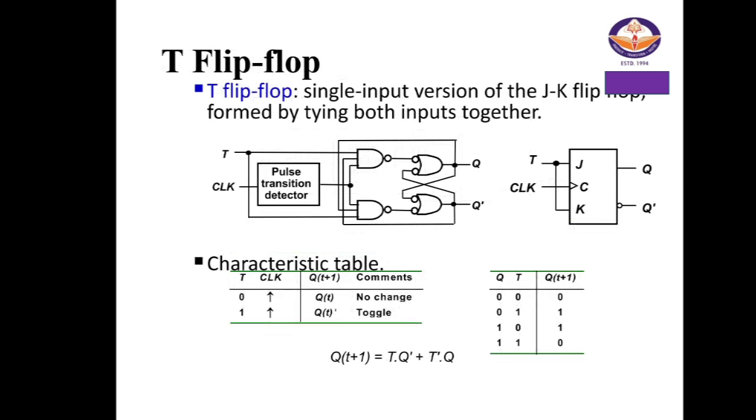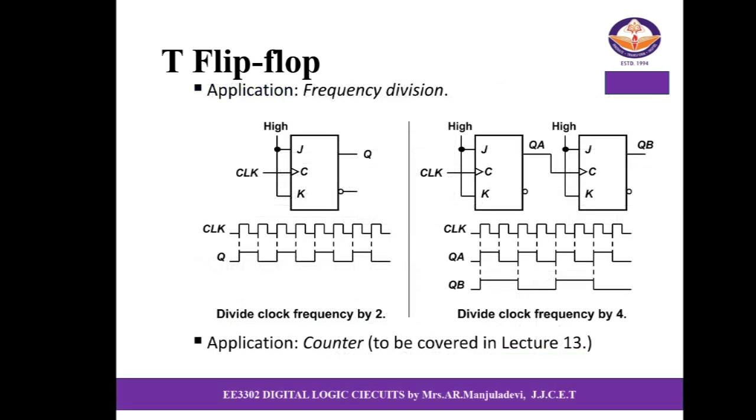Next, T flip-flops. It is a single input version of the JK flip-flop formed by tying both inputs together. This is the logic diagram and characteristic table of T flip-flops. Applications of the T flip-flop are frequency division and counters. These are the logic diagrams and timing diagrams of these applications.